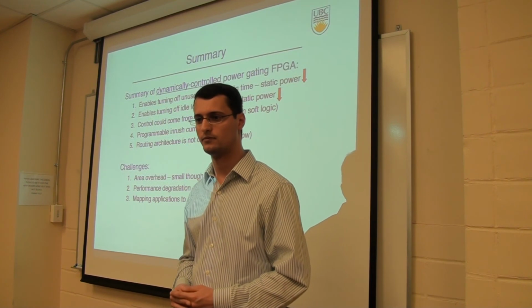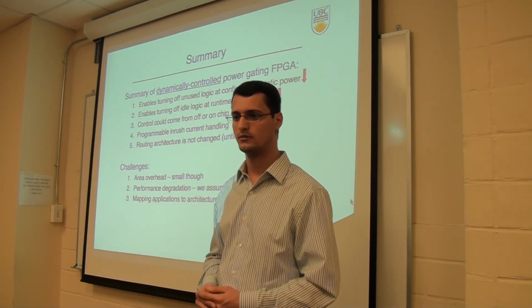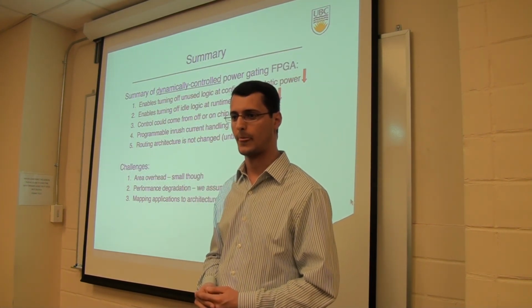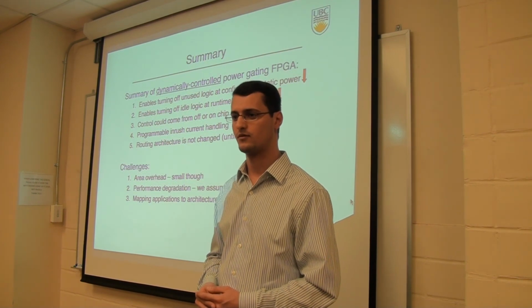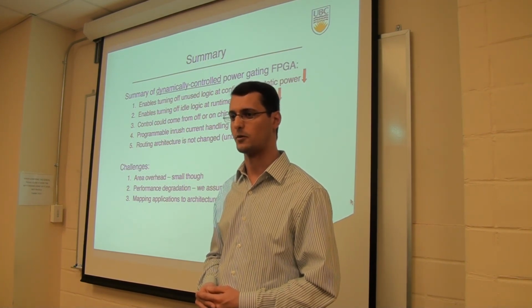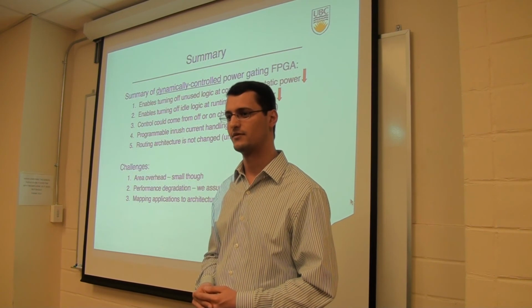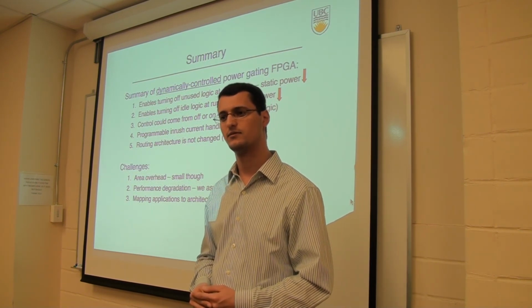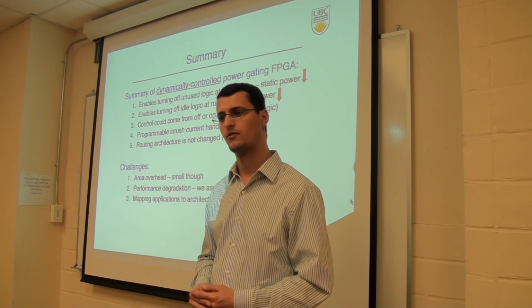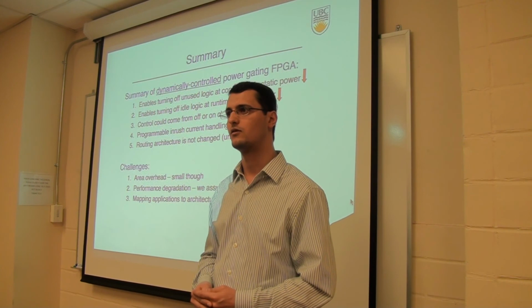Related question: what happens to signals that don't belong to a power region, that are just passing through between two unrelated regions? You don't currently power gate your switch boxes, so they're not affected, but don't the signals go through routing channels as well, between switch boxes? So what happens to those signals which are just passing through? Wouldn't they get turned off necessarily?